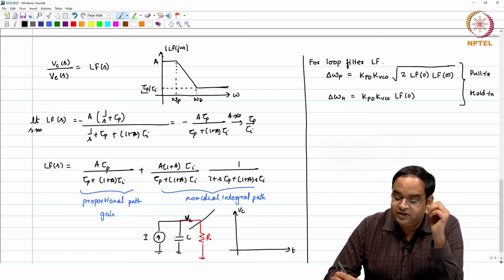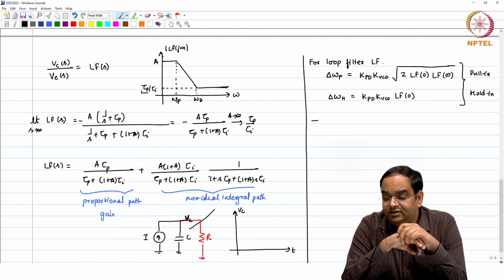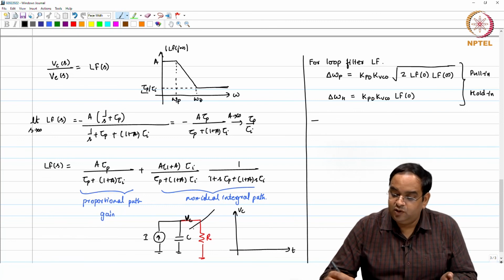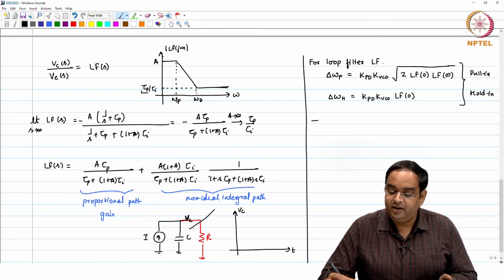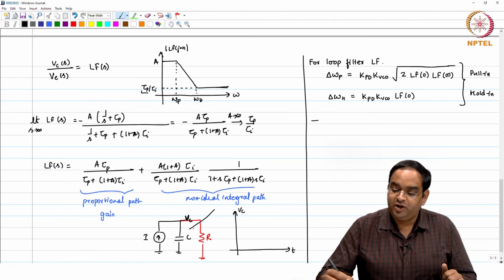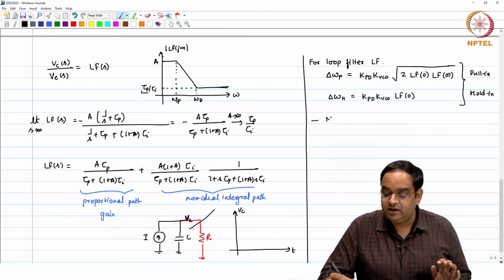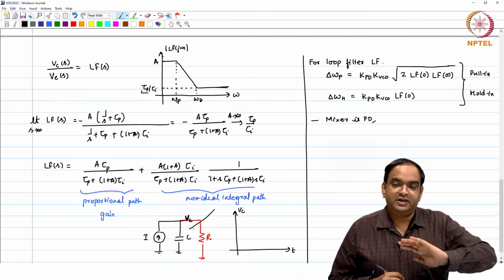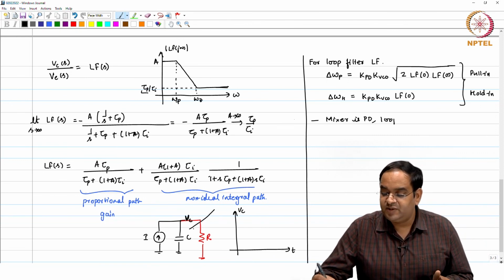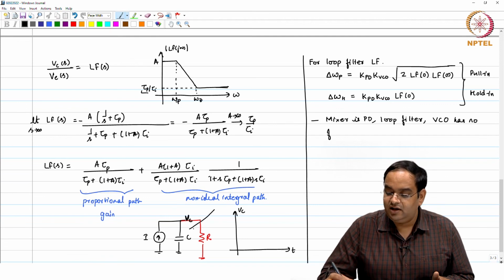One couple of assumptions which we have used in defining all these limits is that our mixer is a sinusoid. So, the pull-in range, hold-in range and lock-in range all depend on our analysis, where we make some assumptions to simplify it. Also, these particular limits are specific to the PLL which we are considering, where the mixer is the phase detector, the loop filter is whatever transfer function it implements, a specific loop filter which we are using, and the VCO has no frequency limits.